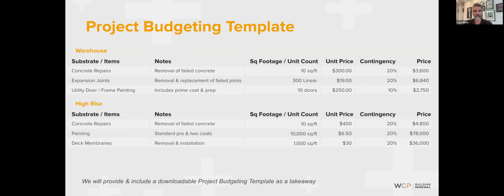Just a quick walk through, looking at the expansion joints, looking for failing paint, looking for the seals around the doors and the windows. So the sealant around the doors and the windows, that's key. If you can get up on the roof, look at the flashing, look at the seals on the flashing caps. Those are the areas that we see all the time on warehouse dock levelers. They rust out. Stairs going into the utility doors if it's above grade. Those are all the areas that you got to keep an eye on a warehouse.